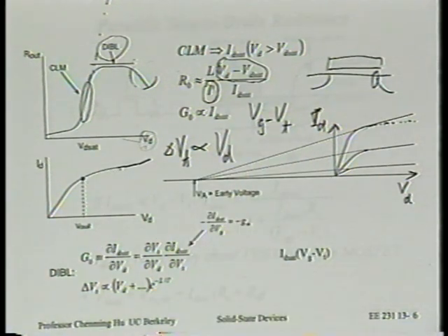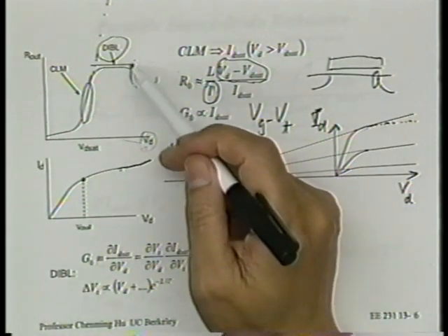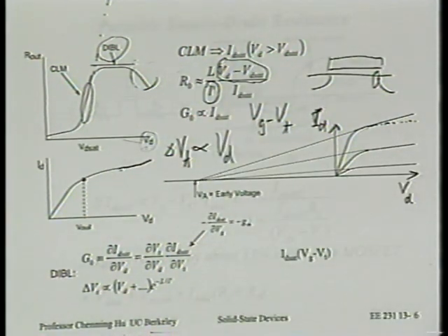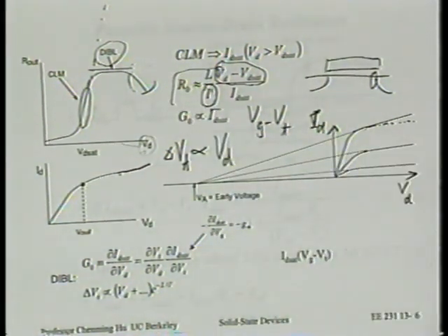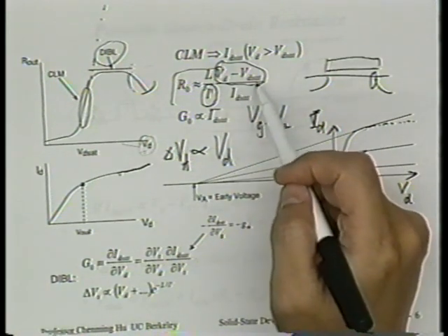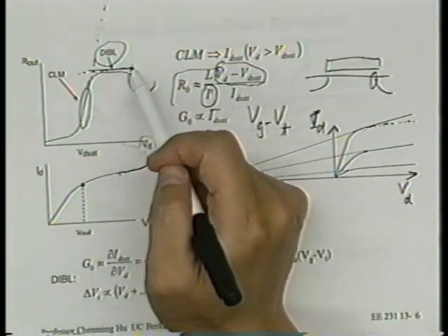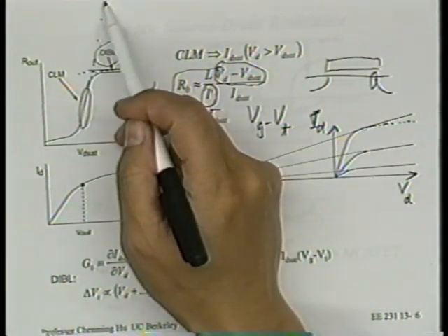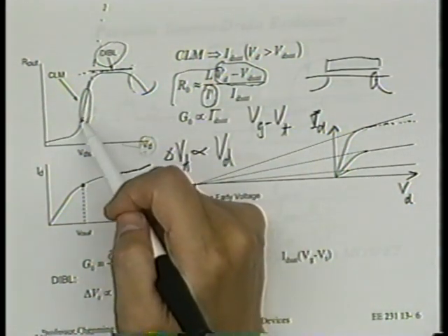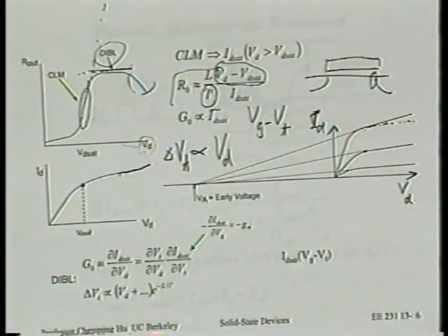Yes. So, as a circuit designer, we'd like to know what is the voltage beyond Vd sat that you can use. Very good. Actually, as an analog designer, we want to know at what point we get to the high output impedance. In other words, you really want to know about this branch. Well, you have a quantitative model right here. Of course, this model could mislead you if you don't consider there's another thing that clips it. You might predict this keeps on going up, right? But certainly this will tell you you cannot stay too close. You have to be how far up? So you do have the model.